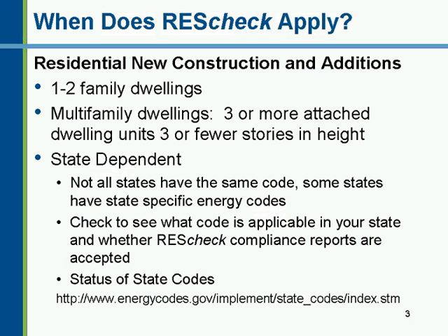So when does REScheck apply? For new construction and additions, you can use REScheck. This is for 1- and 2-family dwellings, or it's for multi-family dwelling units that are 3 or fewer stories in height with 3 or more attached dwelling units.